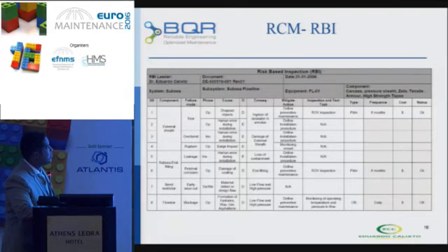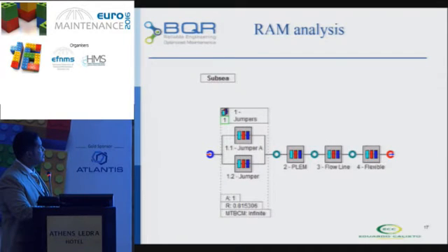So we also performed the RBI analysis based on the FMEA analysis. Here you can see the same failure modes, and for each failure mode, we defined during the FMEA which ones need preventive maintenance, and then we carried out the RBI and RCM. The RBI was part of asset integrity management, and whenever we have unsafe risk, you need to implement that. So here, for example, you have ROV inspection every 6 months. After discussion, what's the best time, 6 months or 1 year? Okay, here is the RAM model.